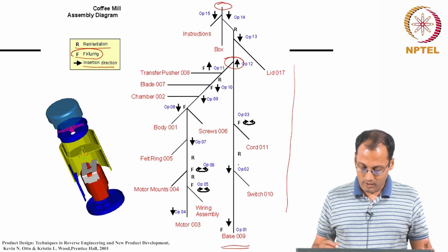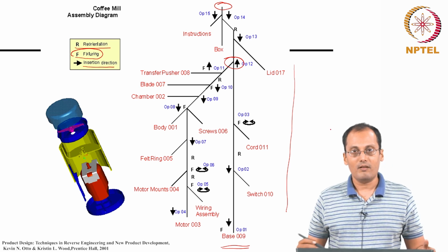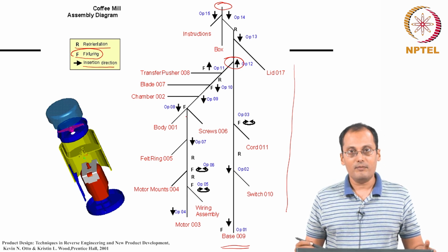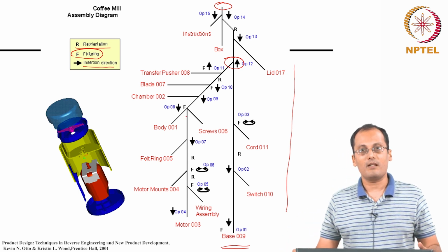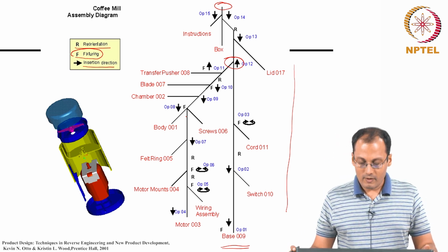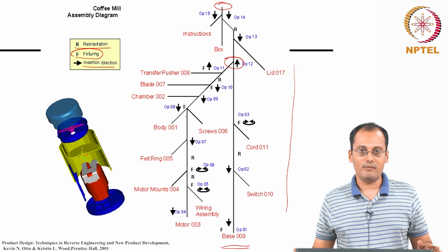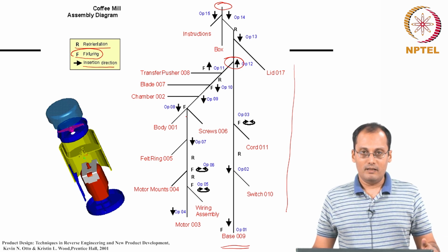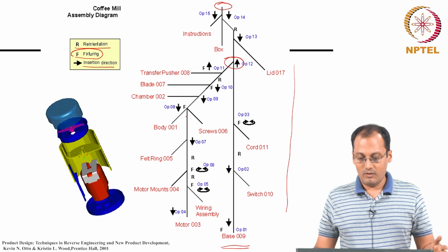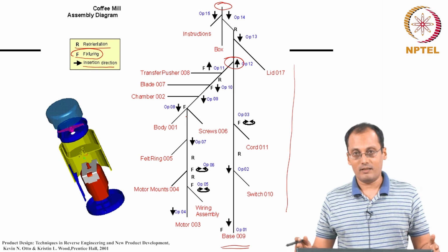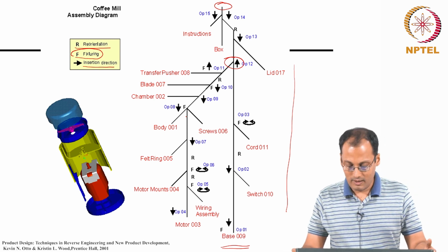Either first one of the sub assemblies or the branches is completed and then the other is taken up, and finally these two sub assemblies are brought in to create the final assembly. So, temporally it can be different, that means in series I can do these operations, or it can go parallel by having two different stations, and one has to see how the times of assembly have to be matched.